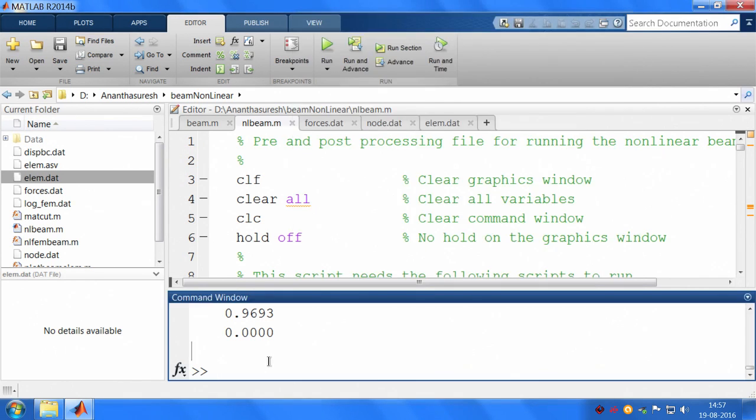So, if I want to look at the y displacement, I have to look at degree of freedom 26, u 26. If I do, it will show this is about 10 micron, 9.69 microns, for the 1 meter long beam that we have taken; with the properties and geometry you have, you can go back and check. It moves very little, very stiff, right.